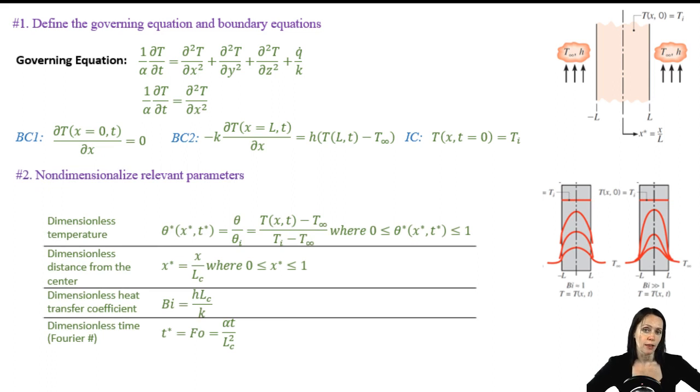Non-dimensionalization of variables allows us to scale up analytically obtained results to real flow conditions. It allows us to avoid round-off errors due to manipulations with really big or really small numbers, and it lets us assess the relative importance of terms within our model equations.